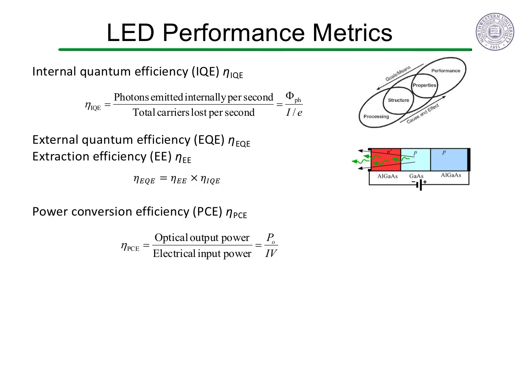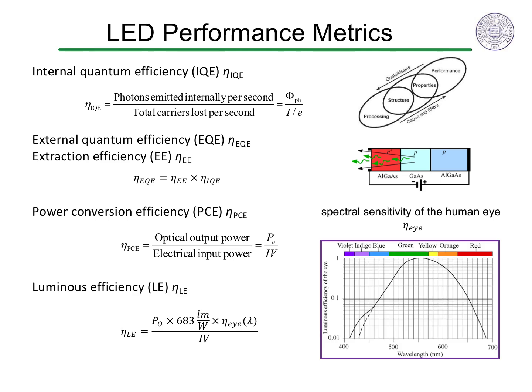So the external quantum efficiency is the product of the extraction efficiency and the internal quantum efficiency. Or the customer could be concerned about the power conversion efficiency, the net optical intensity produced per electrical input power that could include transformer and resistive losses in the entire device. Maybe the appropriate metric is the intensity of light visible to the human eye, measured in lumens per input power. Here, the spectral intensity of the human eye is needed and the conversion of watts of optical power to lumens.